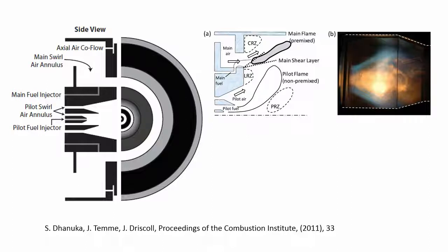This is the twin annular premix swirler atomizer which we have looked at, which powers the GE-NX engine for the Boeing 787. You see that here you have the main flame and the pilot flame. So, it is kind of a mix of different kinds of atomizers. This side is the main air annulus, which is swirled, and this is also the pilot air annulus, and then from here you have the pilot fuel injector.